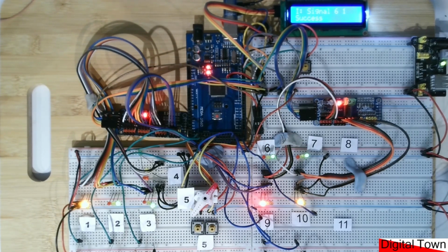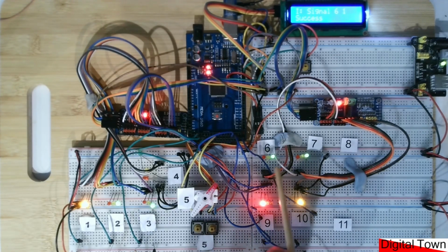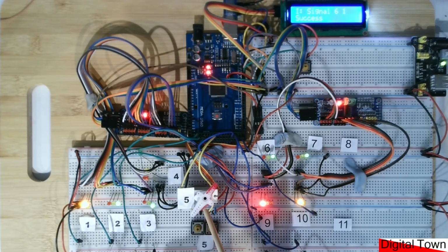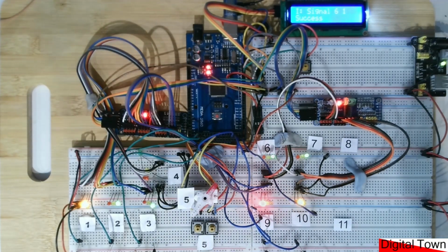Now, the reason for that is you cannot move this turnout or point while you have a green signal, because if you've got a green signal, you could have a train barreling down the track and suddenly he's going to have the track change right underneath him. So part of the interlock system, before this turnout can move, obviously these signals have got to be set appropriately.